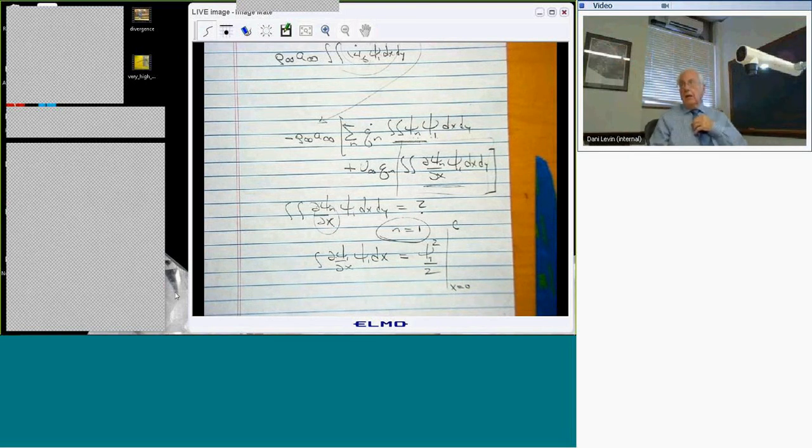For a real airplane wing, that's not likely to be true. But if you have a little skin panel on the wing, if you ever look at the wing and rivets and all that, those panels are typically constrained at the leading and trailing edge. Those panels have mode shapes where this is 0 at the leading and trailing edge. So in panel flutter, so-called, this term is 0 for the same mode, which means that this term doesn't contribute at all.